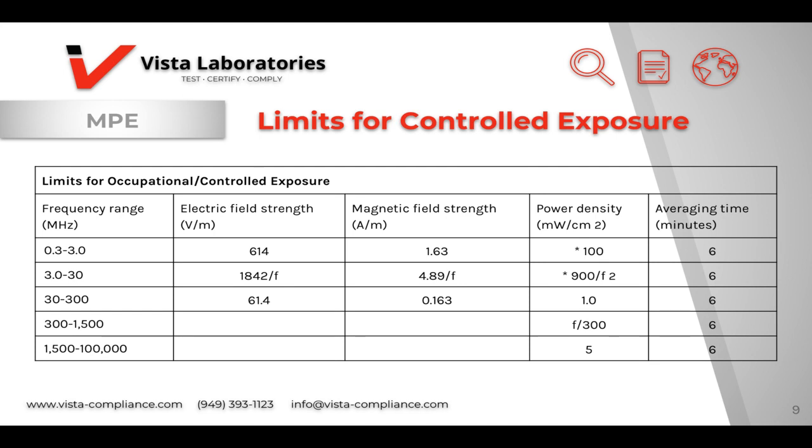Basically, it's the worst case output power of the RF channel requiring the evaluation. When we do the testing, we need to test multiple channels, and some of that can be reduced, but in general, we test multiple channels, and every channel must comply. This is adjusted for tune-up tolerance, so depending on the tune-up tolerance, it can be an even worse case output power.